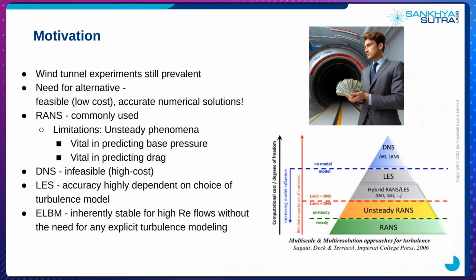The most obvious solution, after taking into account all of these limitations and considerations, is to run simulations with LES models. And while this is a good solution, there's also a con when it comes to using these methods, as the accuracy of your solution is again highly dependent on the choice of turbulence model that the user employs.